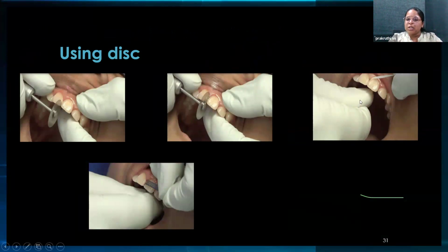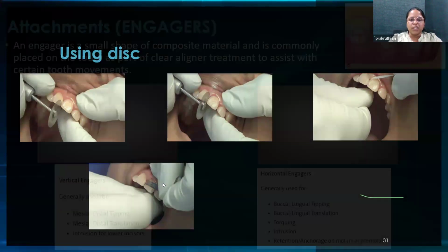After you have broken the contact, take a floss and try to pass the floss between the contacts. If it is fraying or breaking, then some rough surfaces are there. Take a strip and try to further smoothen it.